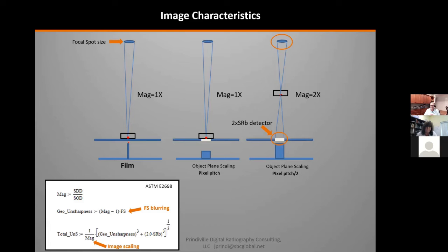So if you say I have a size of 200 microns, and that's going to be my resolution, well, that defect that happens to be that size may actually overlap 2 of those and not necessarily fall exactly inside that 1 pixel. The chances are better that some will not be positioned exactly in there, but slop over to the one next to it. So in that case, you're going to do 2 times the resolution at the detector.